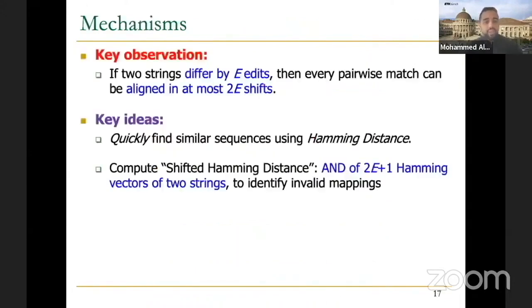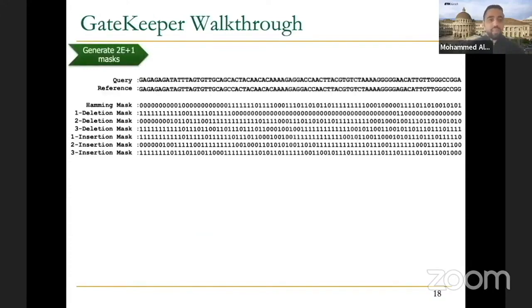All right, so that is the algorithm. And now for the implementation, or how we really implement it on FPGA or on logic gates. So first, let's see a real example with real data. This is the real sequences from the human genome. And what we need to do, this is the Hamming distance calculation, just XOR between the two sequences. Let me annotate it. So these two sequences, and we do first the Hamming distance calculation, just XOR between them, right? And you can see it's 0 where they exactly match, 1 where they don't match in the corresponding locations.